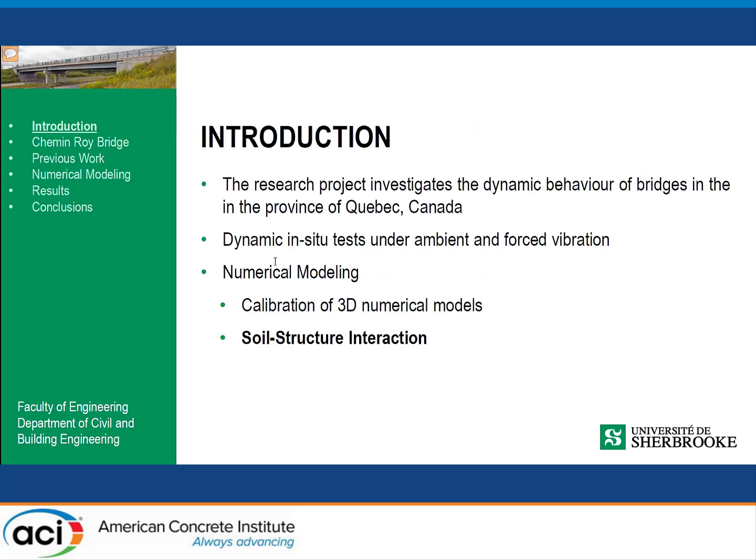In this project, at first we did a dynamic in situ test campaign under ambient vibration and force vibration on three bridges. It allowed us to calibrate the numerical models. In the first part of the project, we calibrated the models on a rigid foundation.